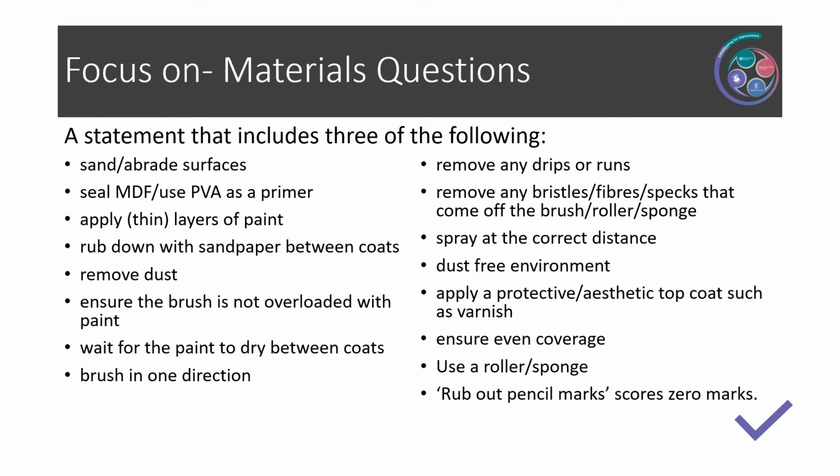Brushing in one direction also makes sure that all the marks from the brush are going in the same way. Remove any drips or runs or any bristles, fibres or specks, because after the paint is dried, these will be permanently stuck to the surface.